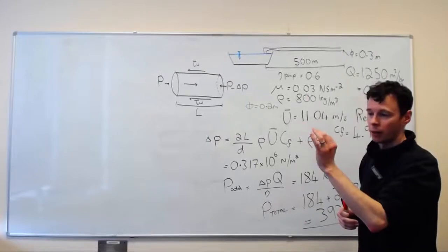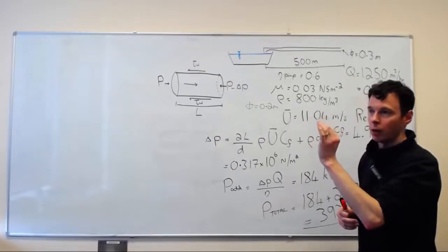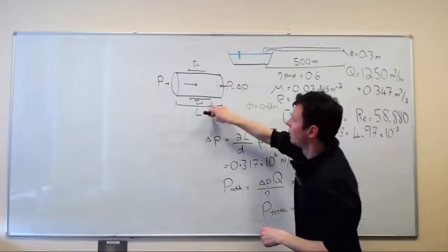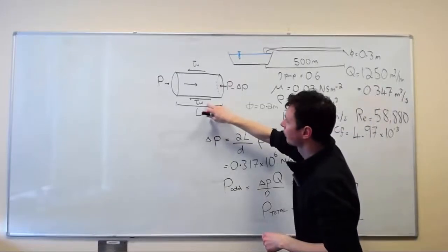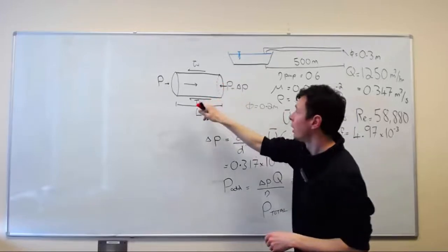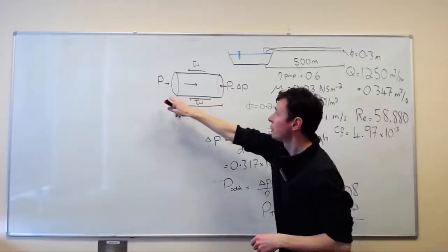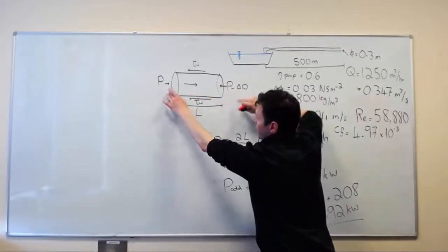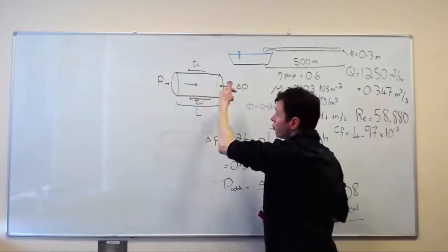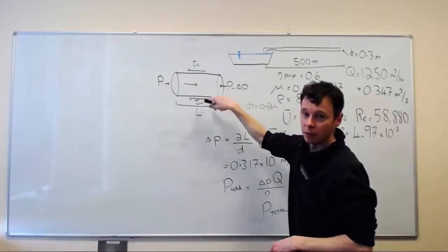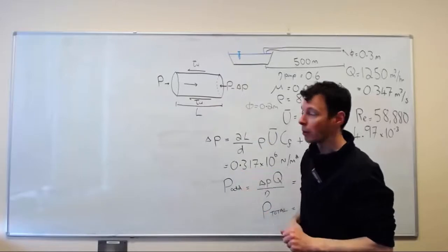When you have a 10 or 8 mil jet, it doesn't matter how big the pump is on the end of it, eventually this shear stress, this opposing force due to friction, dominates. So no matter what your pressure difference, how much energy you're putting in at the upstream end, you can't overcome this. It becomes a limiting factor, so you can only go up to that.